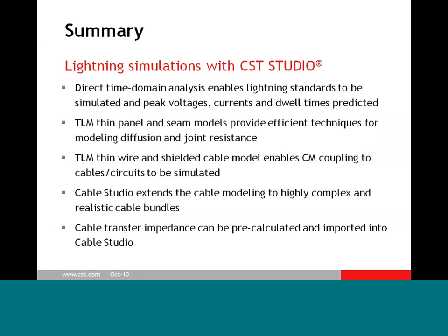So just to summarize then, we've been talking about lightning simulations with the CST Studio Suite. I mentioned that direct time domain analysis, I think, is very useful for this class of problems. It enables us to simulate the lightning standard waveforms directly, allows us to predict peak voltages and currents and the dwell times that are associated with the lightning strike.